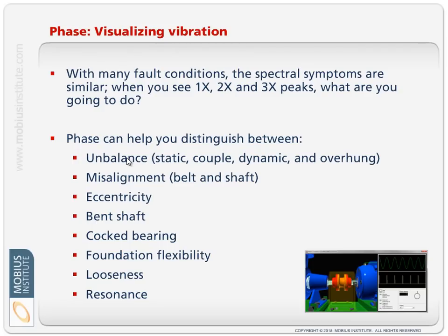But do you know the most common reason why balance jobs fail? Because the machine wasn't out of balance in the first place. Someone sees high vibration, oops, that's unbalanced. Even if it's a high 1x peak, it's unbalanced. And so the machine has to be stopped. A person gets in there, safety issues, all this sort of work, and then they find out it's not out of balance, it's misaligned or something else. So, phase helps us understand that.